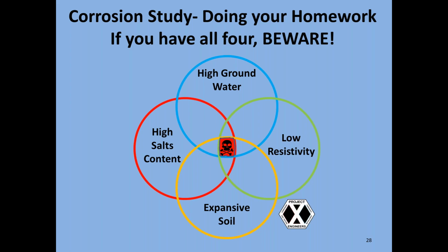Out here by the Salton Sea, there are fissures in the ground that we can drop a 5-foot stake into and it completely goes in there. So you can expect very high corrosion rates, even down to 5 feet, because of this. That's something very important to keep in mind, especially for solar farms and piles. And then the high salt contents: high chlorides, high sulfates, high nitrates, all of those things. The more of that, the more corrosive the site is.